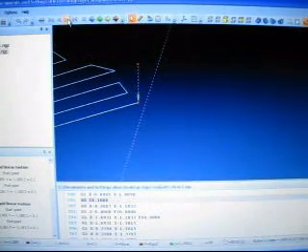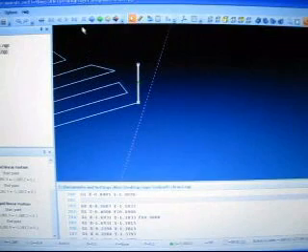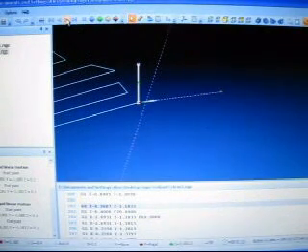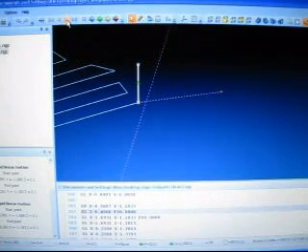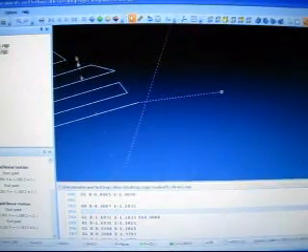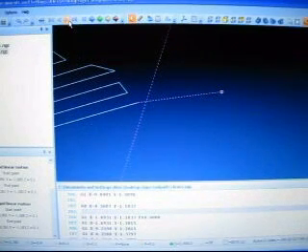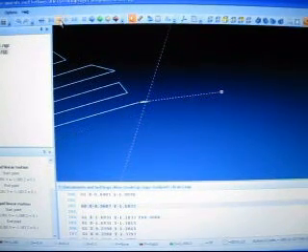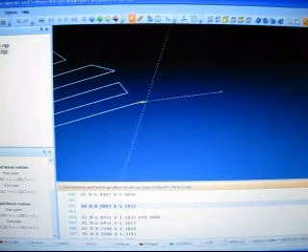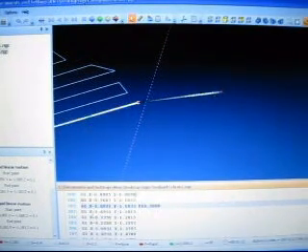So first of all, the rapid motion we don't want. Okay, so that line gets deleted. And then we're moving to that position, we'll save, but we're going to modify that position. Then we've got our plunge motion, but we don't need that, so we're going to delete that. So this line right here is going to have to be modified. Let me just eliminate the spaces between this so it'll run without a space between it.